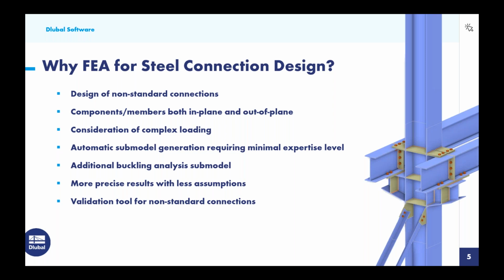The member internal forces at the member ends at the joint will simply be used for the connection design. So no need to integrate those member end forces into an external program. Again, everything is done within this single file. The submodel is automatically generated underneath the hood of RFEM. So this really doesn't require an expertise level knowing how to create these FEA models.